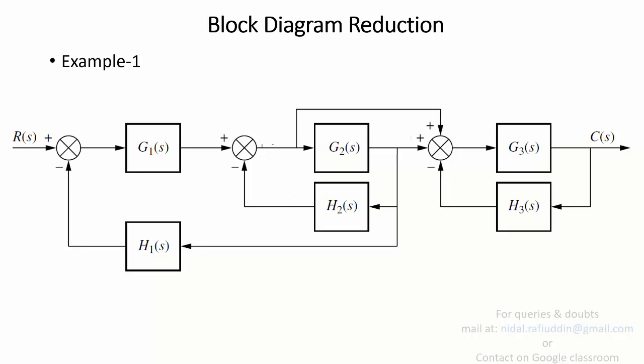Some of you might think to start from one point, and some others may think to start from another point. For instance, if you look at this problem, some of you might think to start from this place. You can see that this is represented by a feedback loop, and you can think to apply the second last rule, which was elimination of feedback loop. And some of you might look at this side and say that we would try to solve this loop first. In fact, this is not a loop, this is a parallel path. And some might start from another place. So it's not really important where you start from. The important thing is that you apply the correct rules.